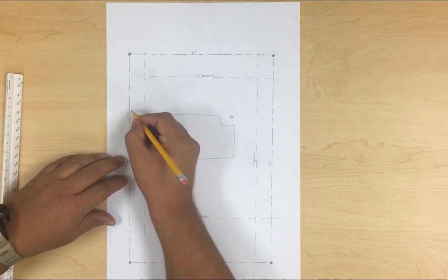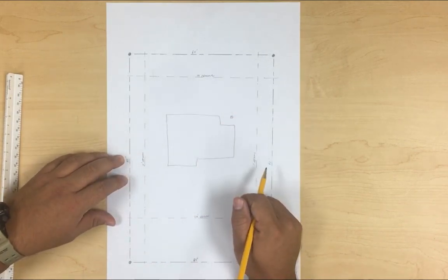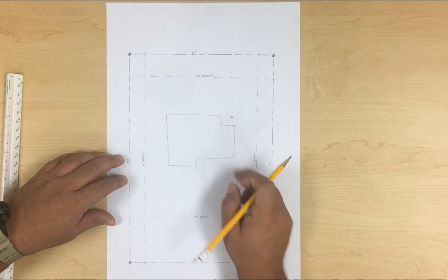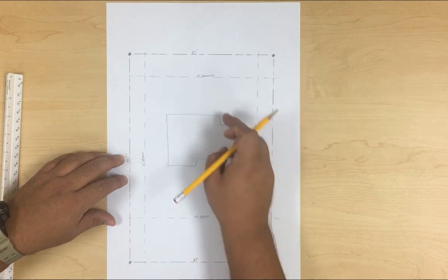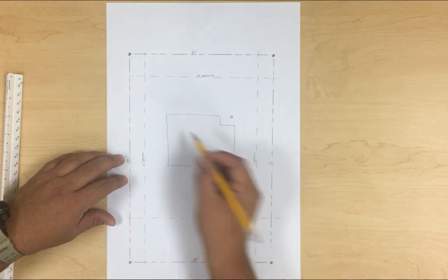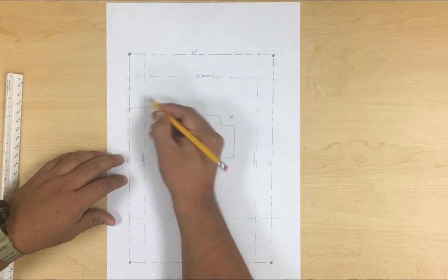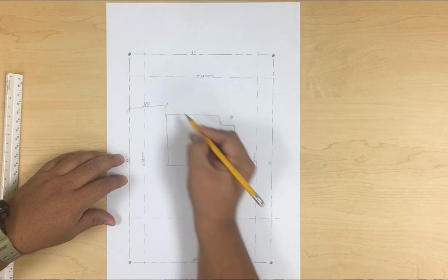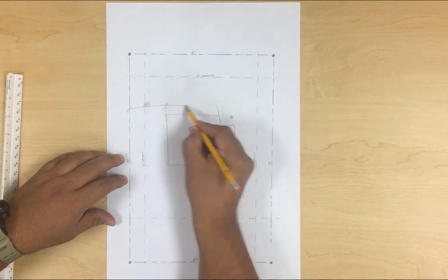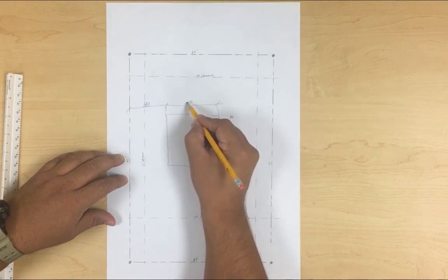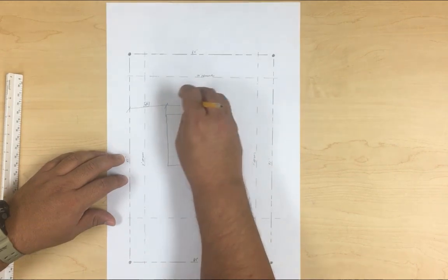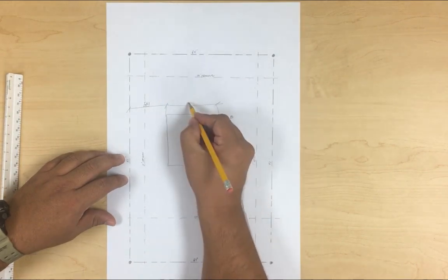What I'm going to do, and actually I'm not going to measure it, you have to measure it. You're going to have to give me a dimension where your house is, not walls, just major breaks, so they know more or less where to put dirt. So you're going to have a dimension from there, and then I'm going to pull another one over here. And again, you should do this with your scale. I'm just trying to make it faster.